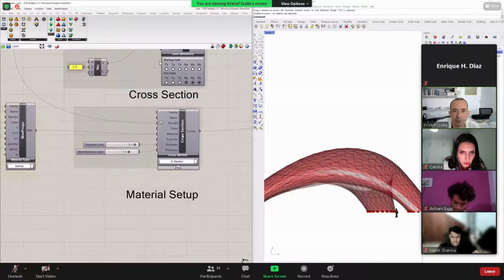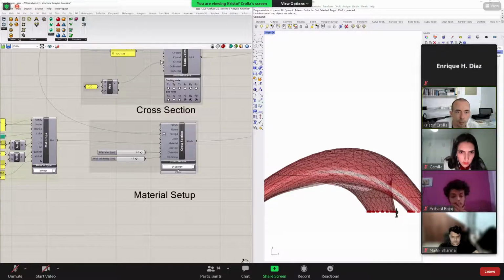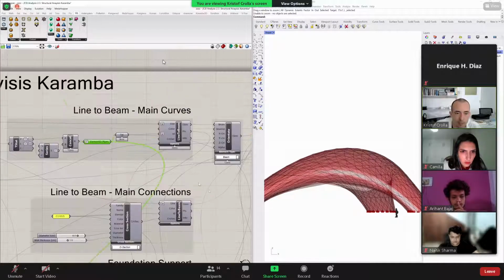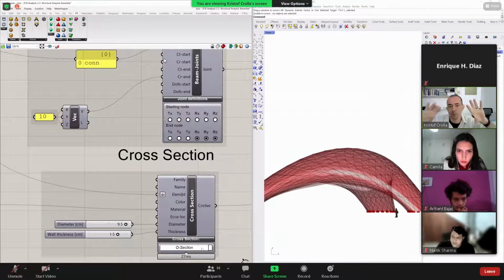And we're applying this to every element with the element ID that I defined here in the very beginning. So every bamboo element is going to be given these material properties. So that's where the IDs matter. Currently, we're setting this to round sections. Note that there's no setup for diaphragms in between, so this is again an abstraction of what bamboo really is in reality. Note that it's also working with a constant section. This is also an abstraction of going from thick to thin.